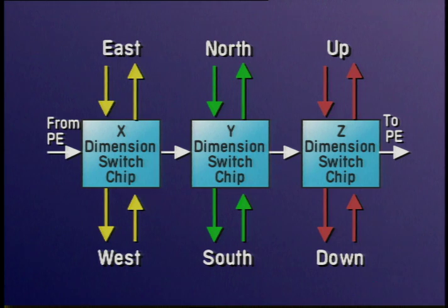Latency of the switch is very low. Essentially, it takes 1 clock period, 6.7 nanoseconds at 150 megahertz, for a packet entering a chip to decide which way it's going and leave again. At these clock speeds, the time spent on the wires isn't negligible and must also be included in latency calculations. In T3D, all wires are either 1 or 1.5 clocks long. Each hop in the network then takes 1 clock for the switch plus 1 to 1.5 clocks for the wire.